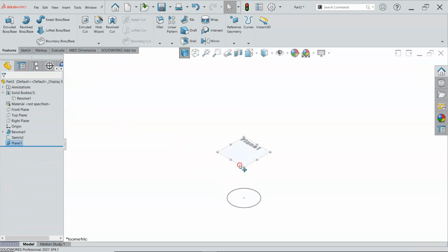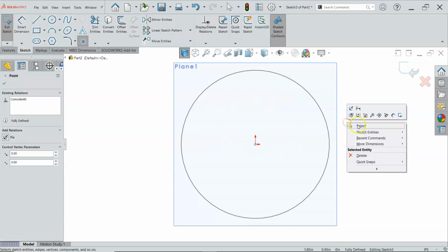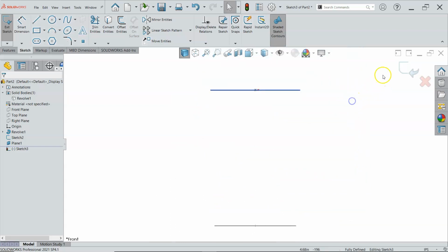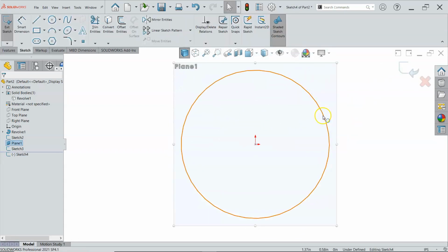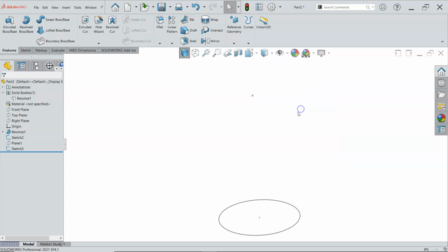There it goes. All right, so if I open up a sketch, this is one of the places where we will use a point. So if I were to put this point off to one side, the loft would generate sort of an oblique, but not really. It's not going to be a true cone at that point. So again, I'm going to accept the sketch, and the loft can have as many cross sections. Oops, got a little button happy there and opened up another sketch. So we'll discard the changes and exit. What I was looking to do was to hide. There we go. Right next to it, we're going to hide the plane so that we can see what the effect of that point in the circle are.